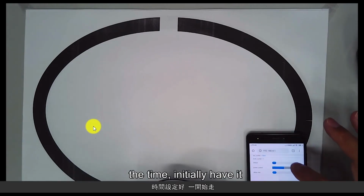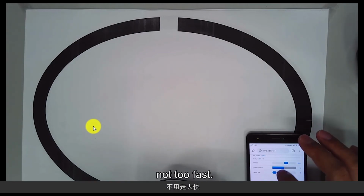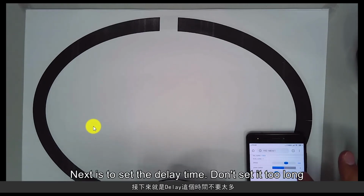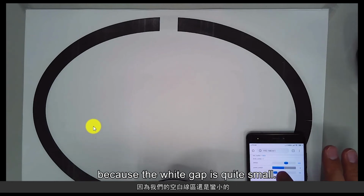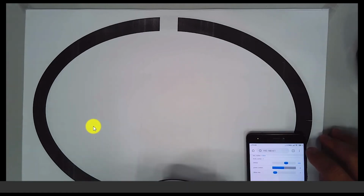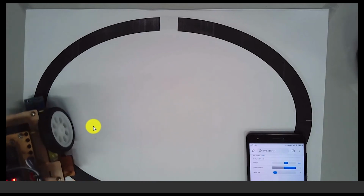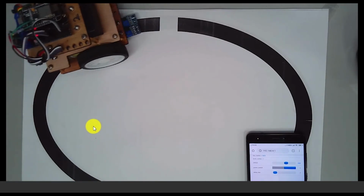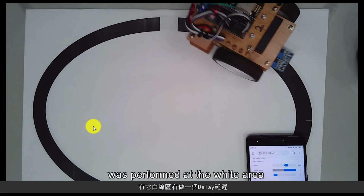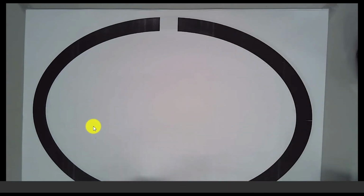First, we will set the speed. Initially have it between 500 and 600, not too fast. Next is to set the delay time. Don't set it too long, because the white gap is quite small. I think that a delay of 7 milliseconds is enough. Let's execute this. A delay was performed at the white area, and it kept moving forward.